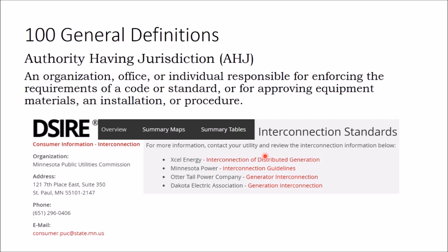So you might design a tiny house that only has 10 amps of power draw for your crazy customer, and you might not pass inspection simply because the National Electric Code does not deem it suitable for habitation because you're being energy efficient with your dwelling unit.